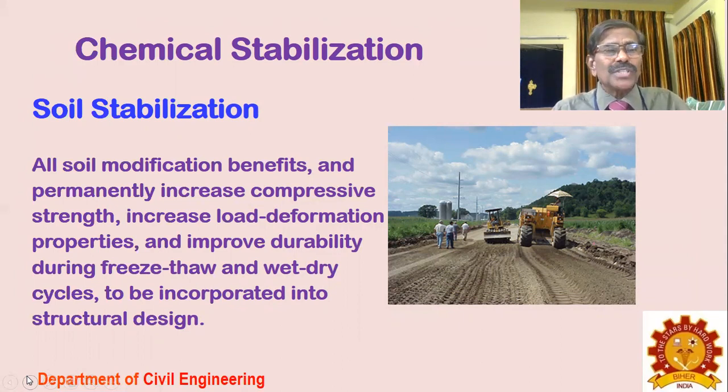The soil is no more just a soil. The stabilized soil is also a part of the whole structure, because load deformation reduces, compressive strength increases, and the freezing and thawing effect is minimized, and wet-dry cycles are minimized, and incorporated in the structural design by itself. So in structural design, the soil effect is also accounted for, the soil-structure interaction, where the soil properties are very much involved in such areas of study.